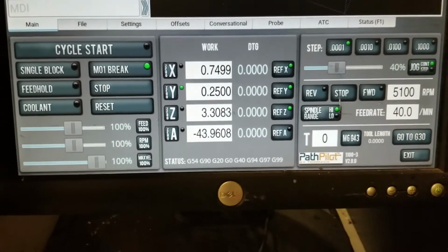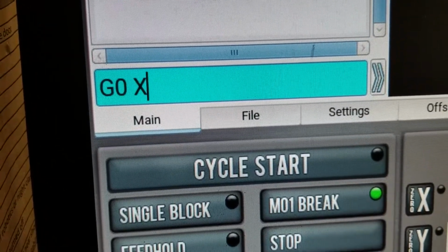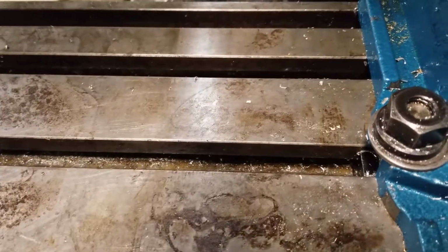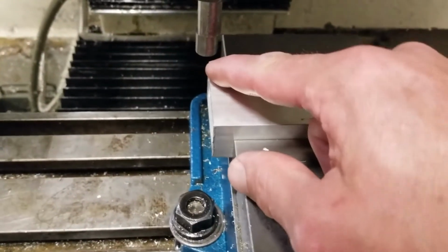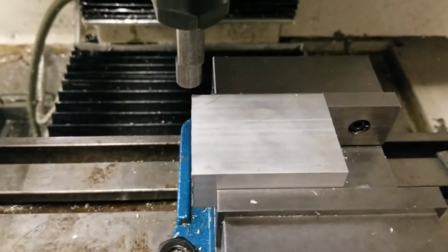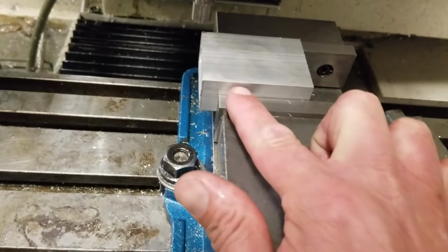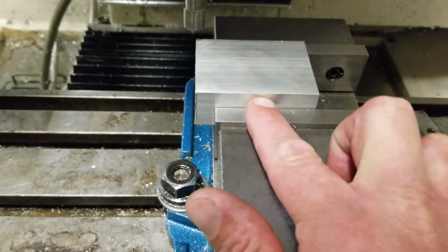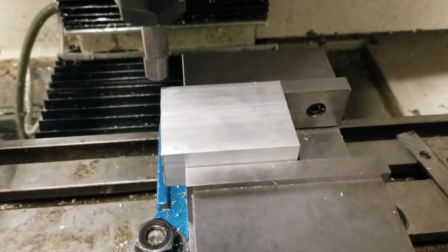Now let's just make sure that it looks right. And you can tell that here it's right on this corner, and that's where my X and Y coordinate is in my CAD model. So that's just a good way to double check that you did everything right, because sometimes if you were probing this side, it would be minus 1/4 inch. So that's one way to do it.